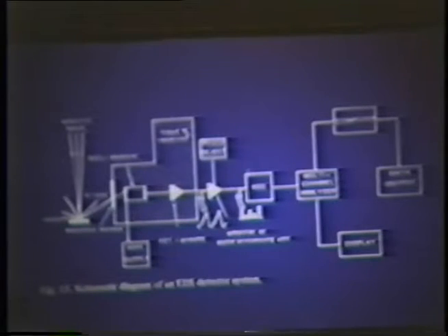Now, the beryllium window in the front here prevents the cold detector from becoming contaminated and absorbs the backscattered electrons. The window also, unfortunately, absorbs some of the light element X-ray photons, which limits the usefulness of these detectors for analysis below sodium. However, there are so-called windowless detectors and thin windows, which obviate many of these problems. If you've been to some of the sessions, there was one yesterday where the people from the Link system showed quite conclusively that they were able to detect even elements as low as beryllium using these energy dispersive systems.